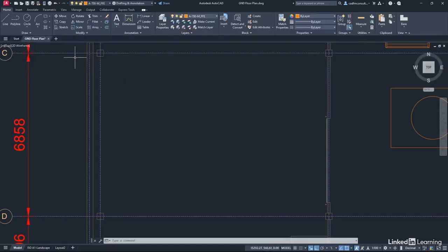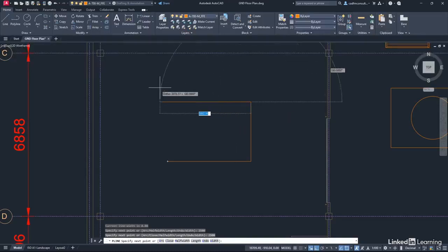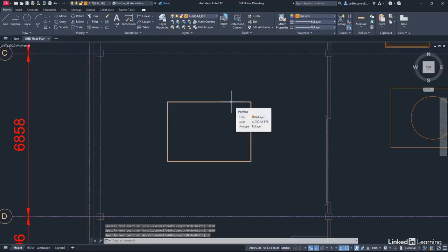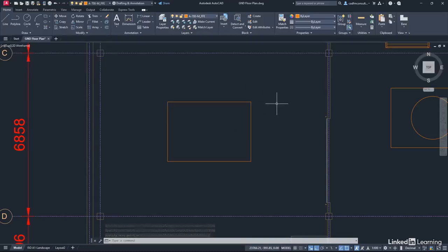So I'm now going to go up to my polyline command here, like so. Come into the drawing area, and I'm going to pick a start point like I did before. Now you'll notice, look, I move the mouse around, I can only go horizontal and vertical with ortho. So I just drag along, I type 3500 in the direct distance entry there. There's my line, and I can just drag up vertically 2500, enter, drag to the left, 3500, enter, and then it's a right click and close. There we go. And that is now still a closed polyline of the same sizes that we did before.